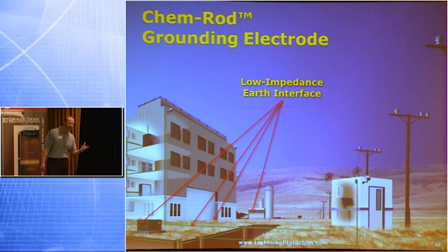And again, we want to have good low impedance common grounding practices. So when we look at a site, are they using good grounding practices? Is everything bonded, tied commonly together? So the grounding system is working as a team, and is it achieving a low resistance ground? The standards don't address that. We believe that you do want to have a low earth contact. I like to tell my clients, especially for a guaranteed system, we want a 5 ohm or less ground.